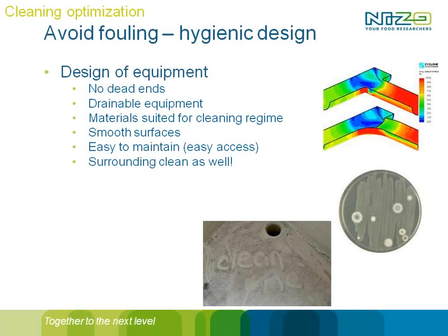Moreover, your equipment should be drainable, so try to avoid a layer of water or remaining product or cleaning fluid or whatever inside your equipment. After cleaning it should be clean and dry, or at least no water or no product or cleaning fluid left inside the equipment. The materials should be suited for your cleaning regime.